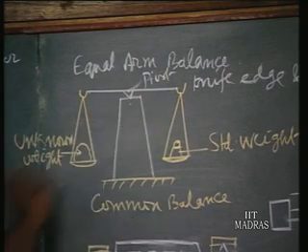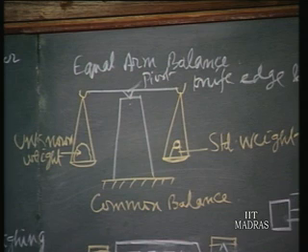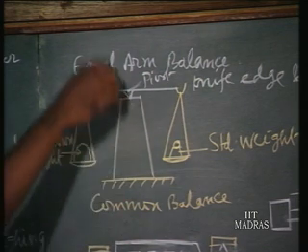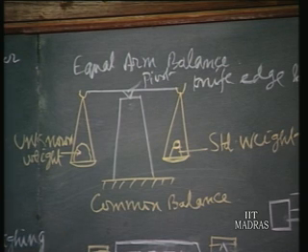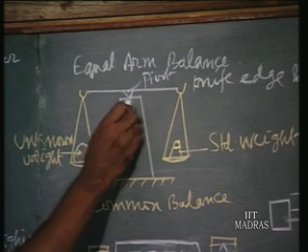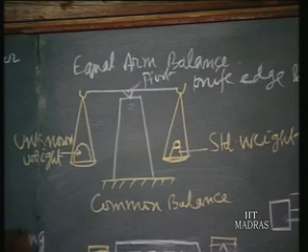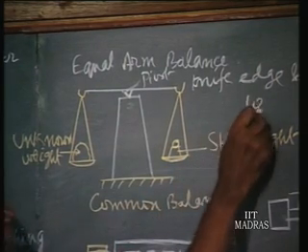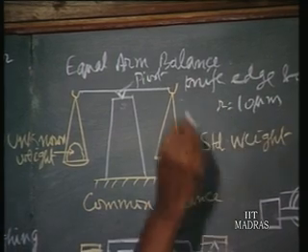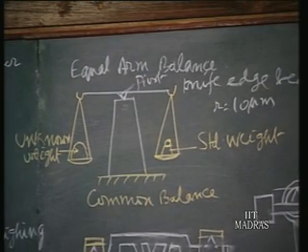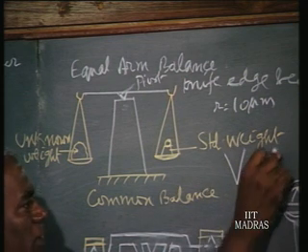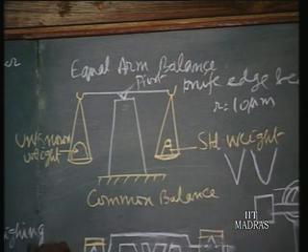The support is sometimes made of synthetic crystals or something like that, synthetic diamond is made use of, or a more hardened metal is taken. Otherwise, the knife will plow into this support. To avoid it, the pan or support is harder than the knife. The knife end is not a sharp end, but it is always rounded to a radius of the order of 10 microns.